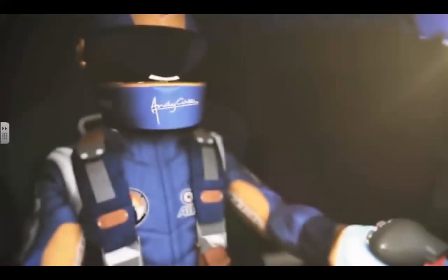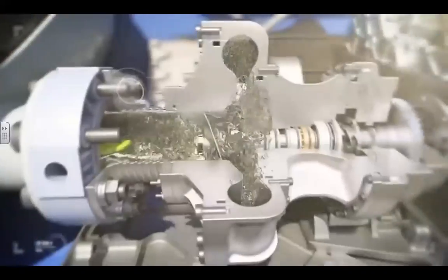Similarly, more unconventionally, you might have heard of the Bloodhound, which is a car that's being developed that will supposedly go 1,000 miles an hour. Now, it obviously has jet engines, and it has a rocket engine, but you may not know that the rocket engine actually has its fuel pumps driven by a regular internal combustion car engine, right? Because they need to pump the peroxide fuel into their rocket combustion chamber. Whoa. This rocket car has an internal combustion car engine to drive its turbo pumps.